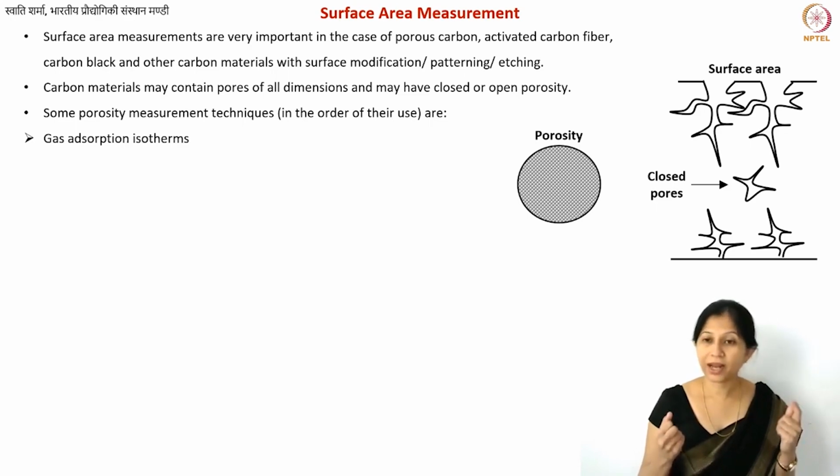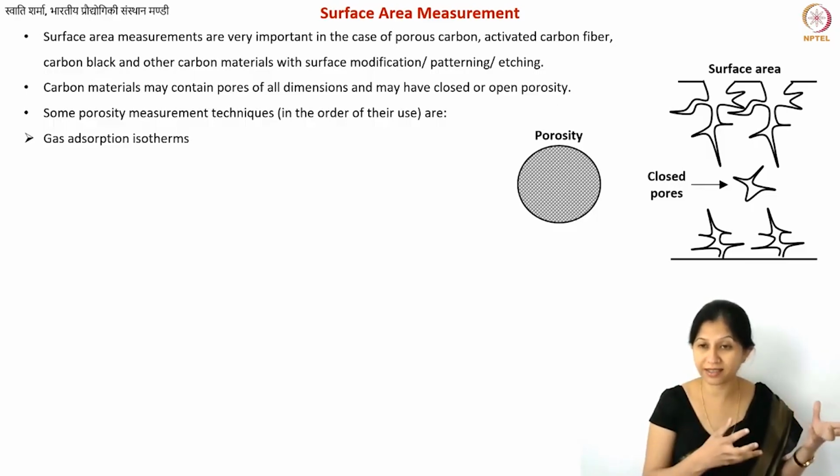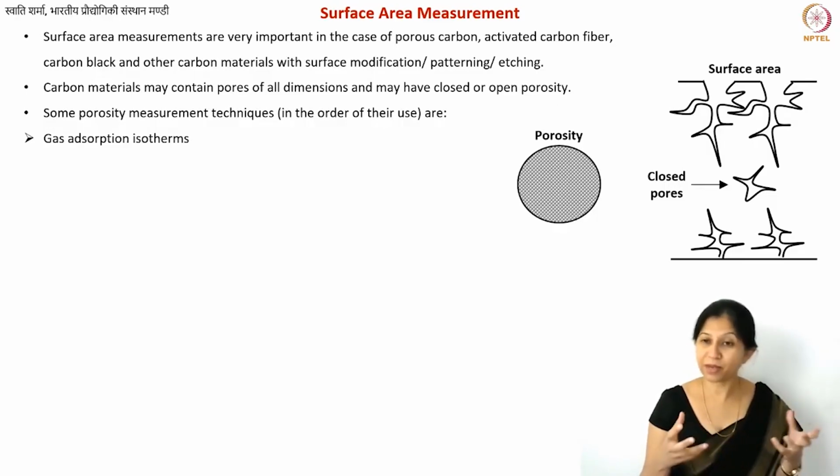How do you measure that? Well, one easy way to measure that is to observe the change in the pressure of the gas, the partial pressure, because that is very much possible. The equipment that we have, I'm going to show you a schematic on the next slide. This equipment basically utilizes inert gases, in most cases nitrogen, or argon also in the case of carbon. Here and there you will see argon. So you will have these inert gases which will go and sit on top of the surface on the porous carbon sites, and then you will basically measure the difference in the pressure, the initial pressure.